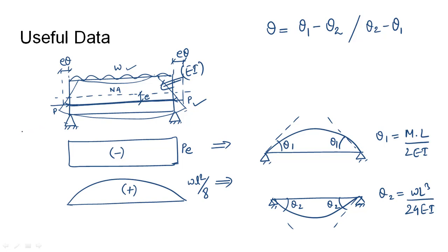This is obtained as delta x equal to radius into the deflection. Here the radius is nothing but the eccentricity value, which is E, and theta. So delta L of the pre-stressing cable will be equal to 2 times delta x, which is E theta. This would be obtained as 2E into theta. Here theta is the net change in deflection of the beam at either end.